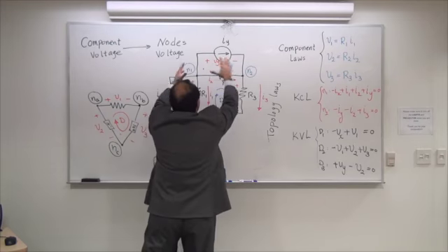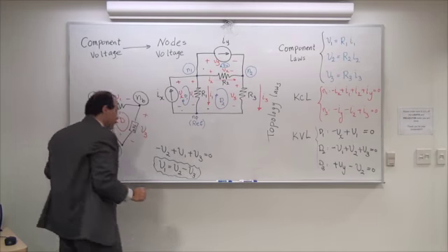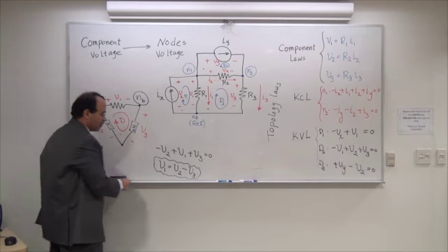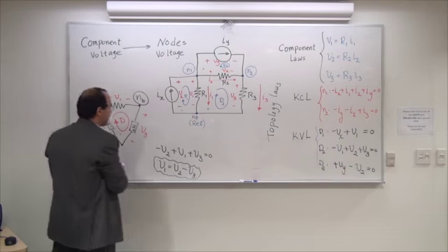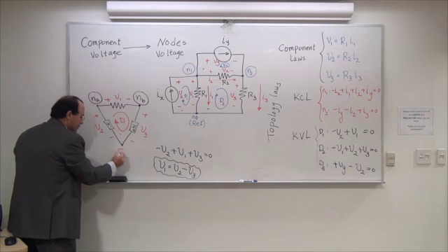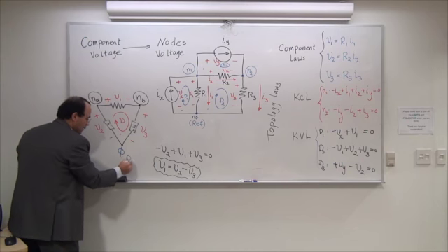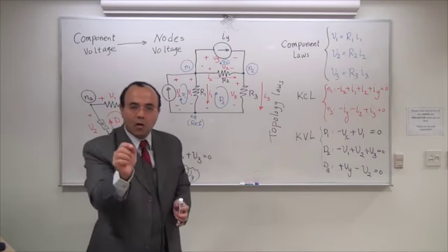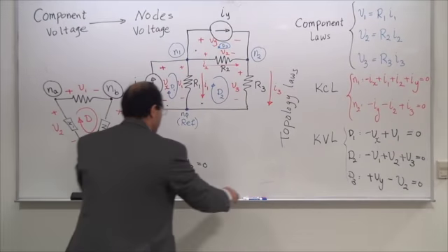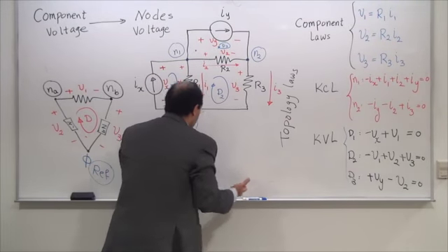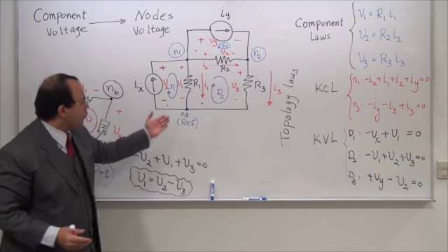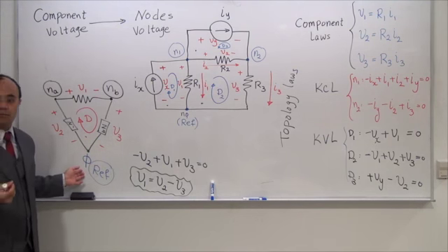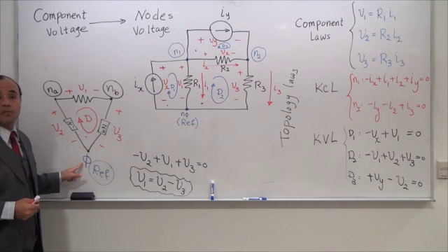As soon as you have a system in front of you, you are going to pick a reference node. If I pick this one as my reference node, which is the same as what you will see here, this is going to be my 0. I'm going to pick the reference node and assign 0 voltage to it. Previously, all I did was ignore writing the yellow for the reference node. Now the reference node begins to make sense to me. This is a 0 voltage.